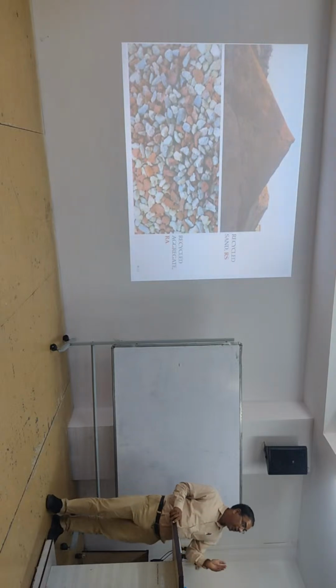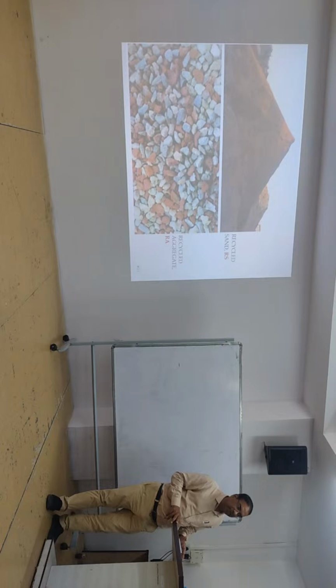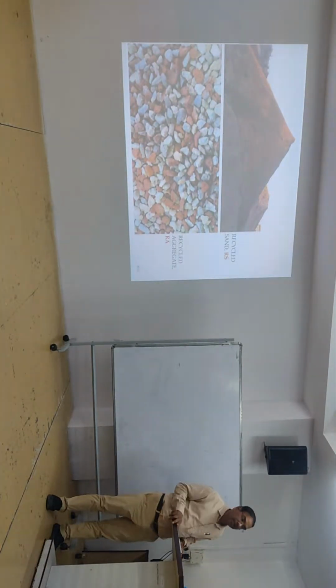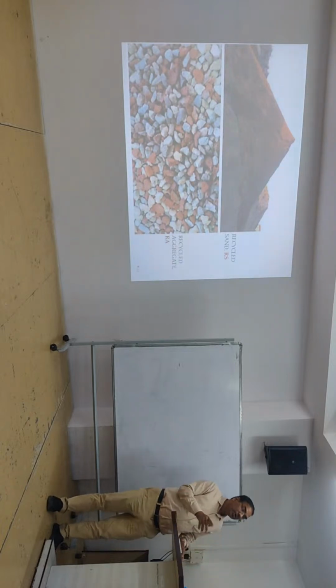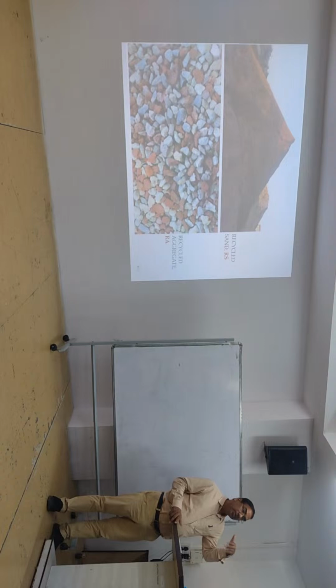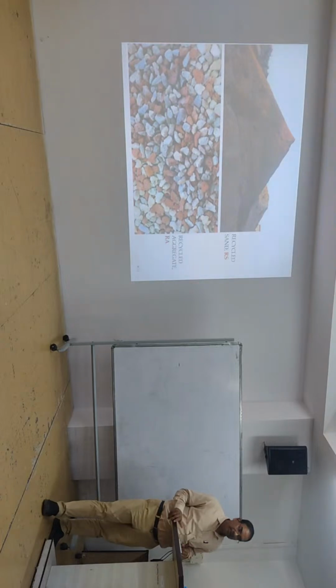So we are using it under its capacity and misusing it, not utilizing 100%. We should use aggregate only in the top layer, where we need 120 CBR, but we are using it for only 10 or 30 CBR.